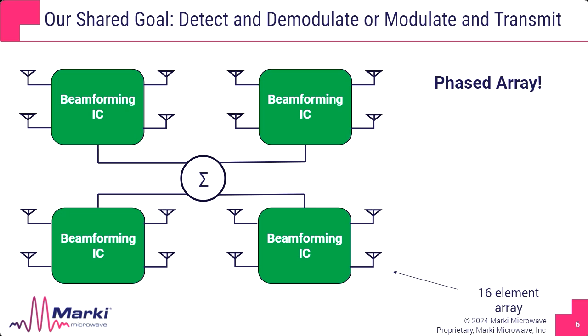And that allows the system to steer a beam with directionality by adding signals in phase in certain directions and canceling them out of phase in other directions. And you can now scan this complex environment much faster and track multiple things with less interference.